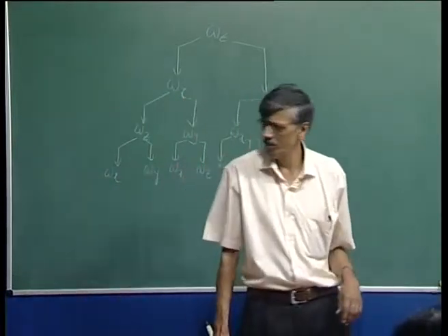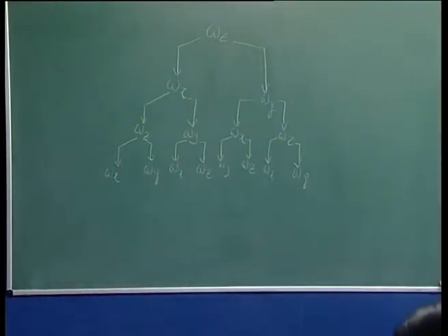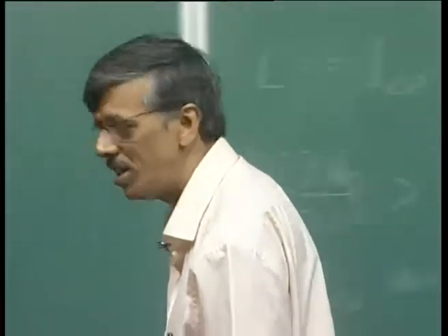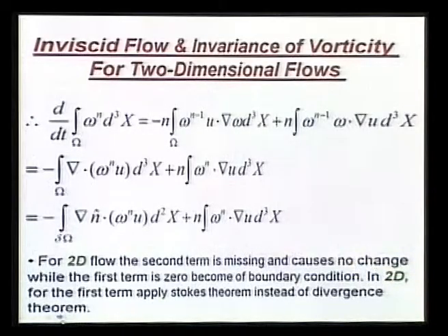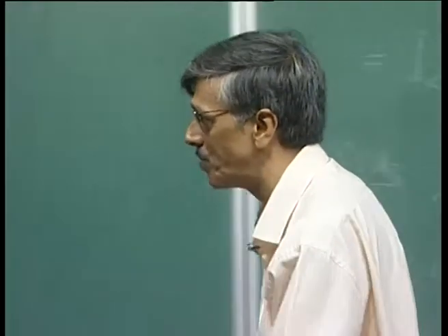So, this is the one thing that we can establish for 2D flows. For 3D flows, you can very clearly see the time rate of change is given by this, the stretching term. So, stretching has a very, very important role to play for 3-dimensional flow. It can tell you how the various moments of this vorticity can change with time.